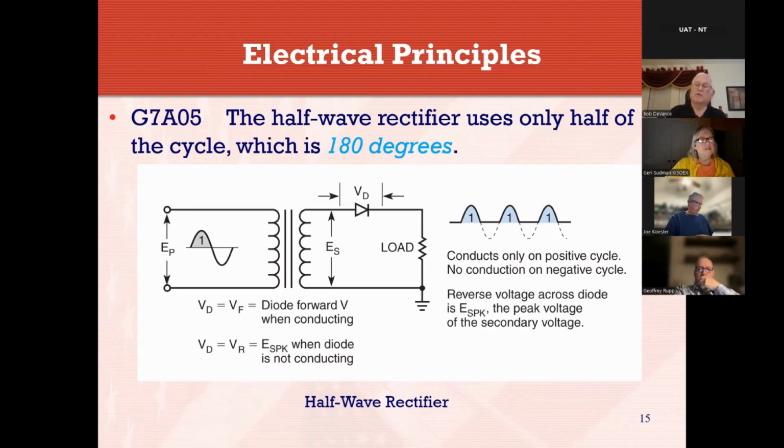Many of the switching power supplies have a tuning knob on them. So if you're getting a noise at a particular frequency, you can move that little knob and move that particular birdie, as it's called, to someplace else so you don't hear it. Good point. Mine does not. I'm sorry. I don't have one of those, but I just wanted to confirm that because switching supplies are so much cheaper. Yeah, exactly. They can be made with lighter, smaller components, and they're a lot cheaper in the long haul than the big transformers. That's basically what it boils down to.